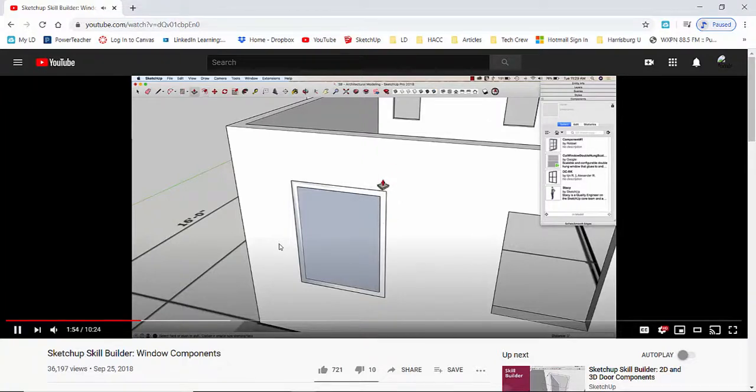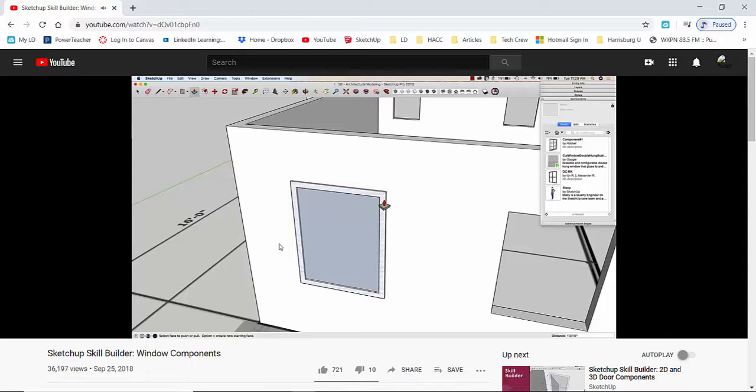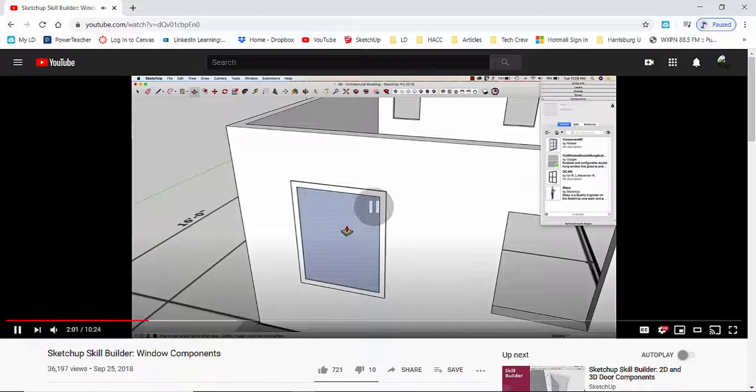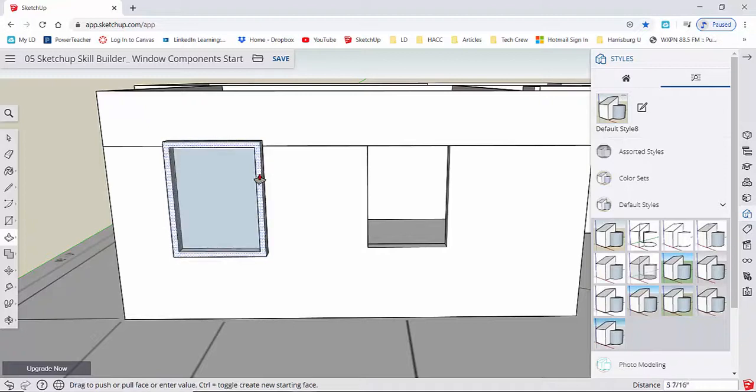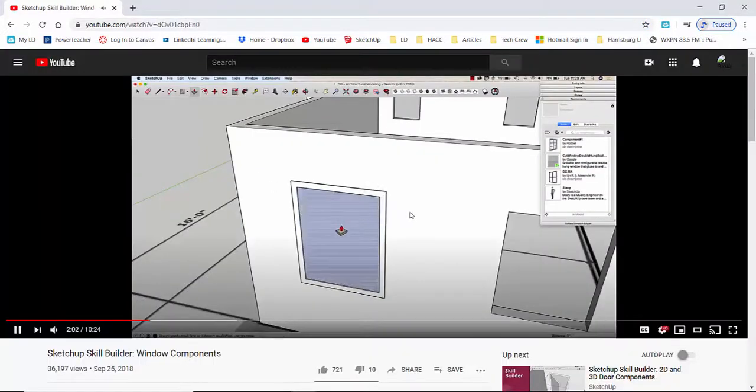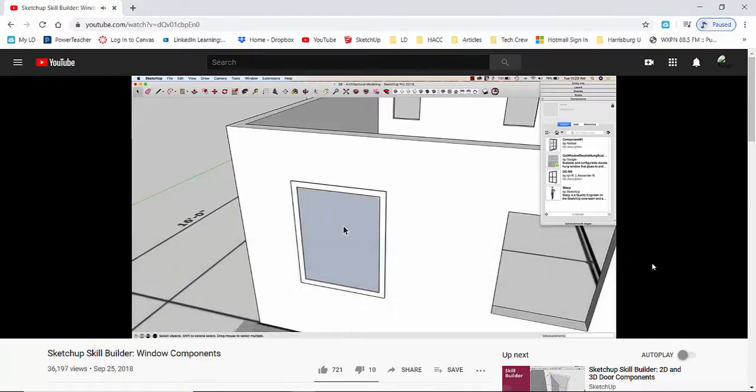Something like that. I could take that then and pull it out. We'll say a half inch. With the push-pull tool, click on your outside border, drag it out 0.5 inches, enter. And I can get rid of this surface right here. Or no, you know what? Better yet, let's take that surface, reverse it so the proper side is facing out, and then fill that